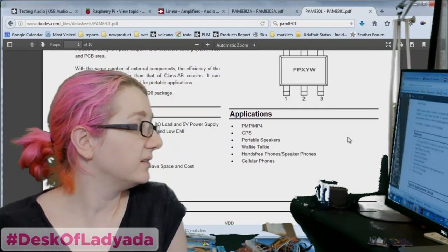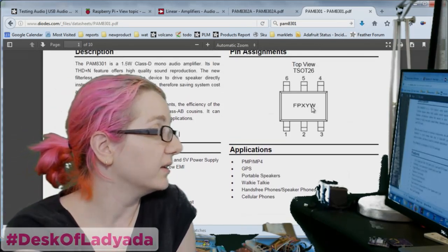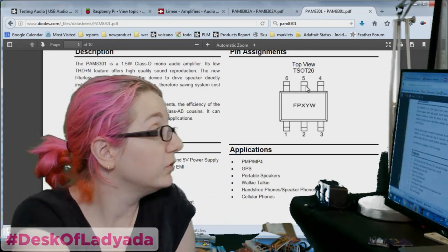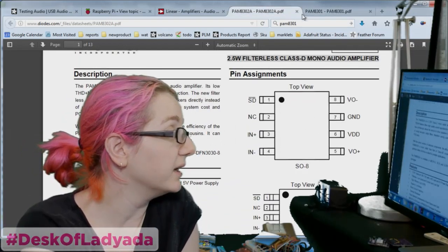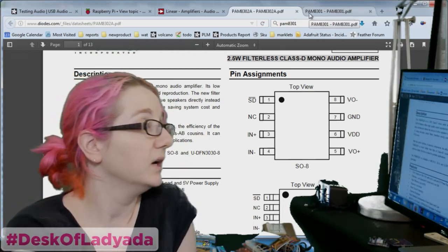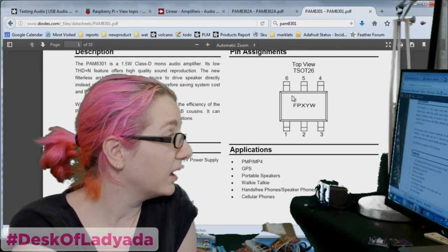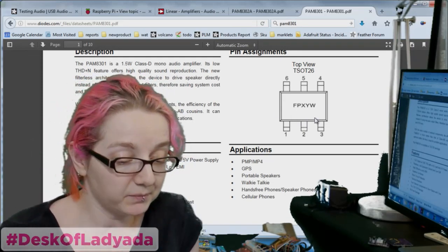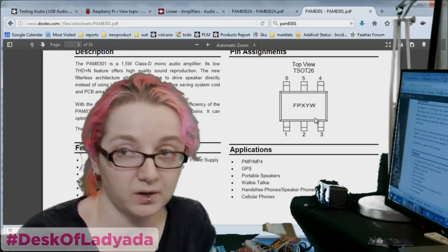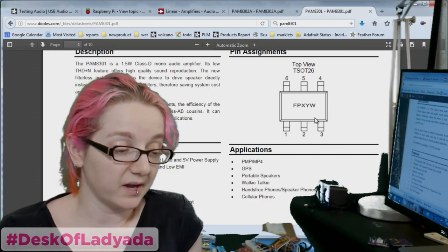The only thing that it doesn't have, that the original one does, is the PAM 8302 has a negative input reference, which can help reduce noise. And I might need it, but you might also not be able to notice a little bit of noise. So I'm just testing it on a breadboard right now before I go crazy and actually design a circuit with it.